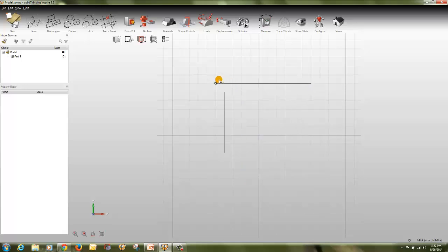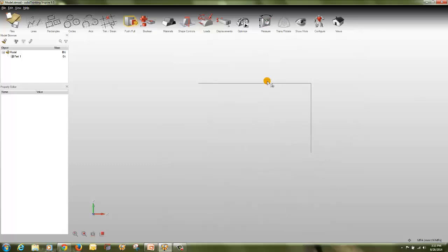So before, just right click once to edit these points. If you right click twice, you cannot move this. So the parallel line can be moved parallelly. You cannot move it diagonally, it's a constraint. So in this way you can move it. Once you right click again, it will get finalized, as you can see. So this is the final line.